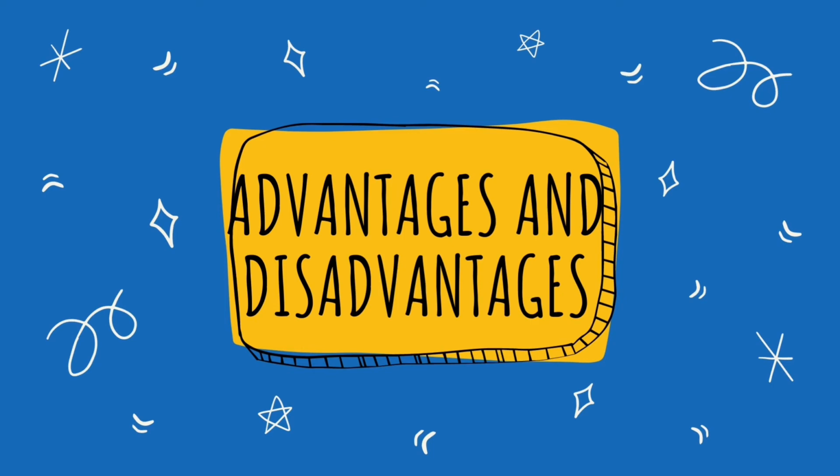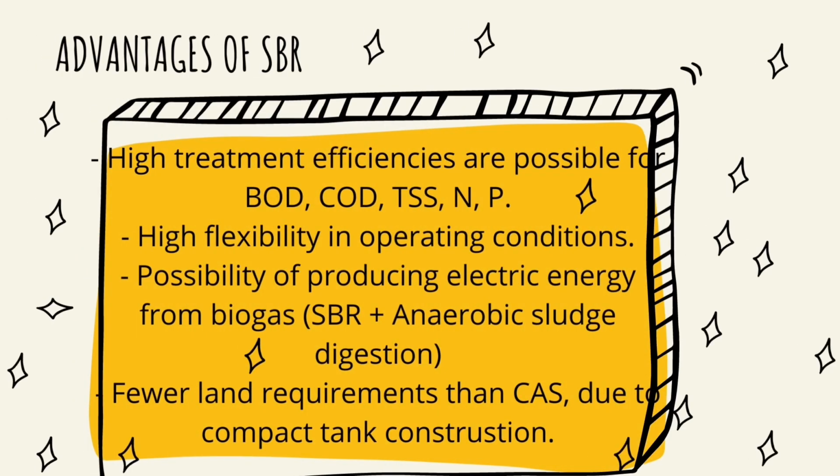Lastly, we're going to discuss the advantages and disadvantages of our reactor. There are several advantages of the sequential batch reactor, or SBR. First, the reactor has high treatment efficiency, possible for BOD, COD, TSS, and also P. Second, it also has high flexibility in operating conditions. SBR also has the possibility of producing electric energy from biogas. And finally, SBR uses less land than CAS due to the compact tank construction.